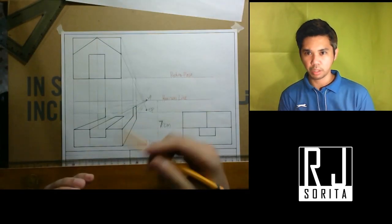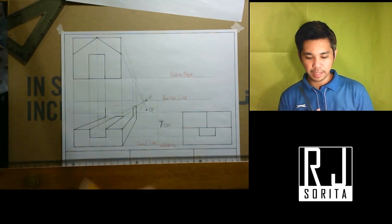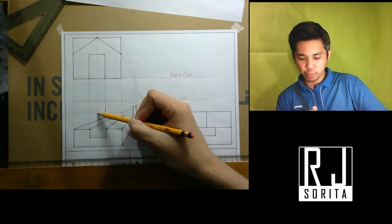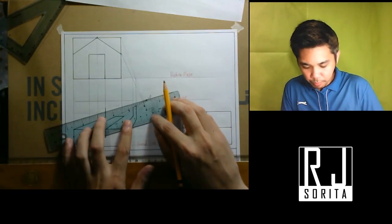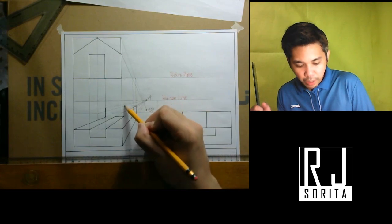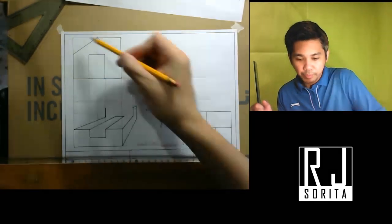Are you able to see now how our object is forming? Now what I want to do is to project this line. We can project this using the station point. However, since I've already projected it downwards, what I can do is from this point, just connect it to the vanishing point. So if I connect this to the vanishing point, I will be able to determine where it lands at the far end of our object. See, this is the line. This line is this one.